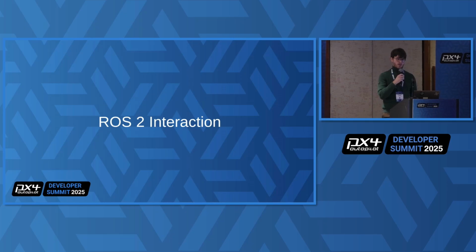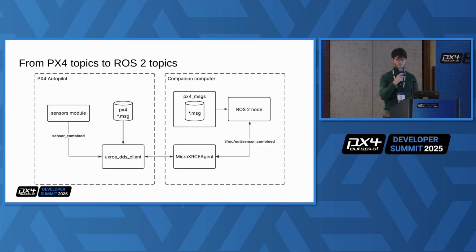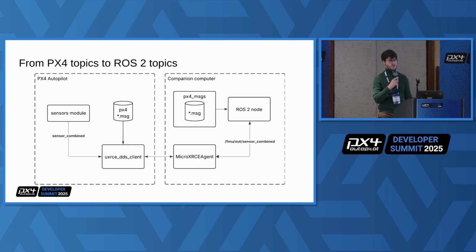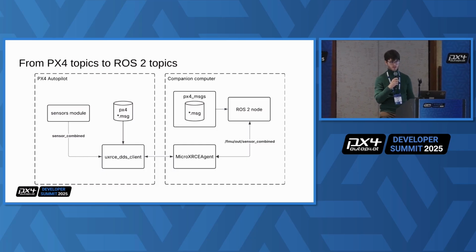Okay, at this point, you should have the client and the agent nicely talking to each other, and you are ready to actually do some real stuff on top of that. So how do you now interact with ROS2? The most important part is that ROS2 nodes need to know the message definition for your PX4 messages in order to properly deserialize and serialize them. Those message definitions are contained in the